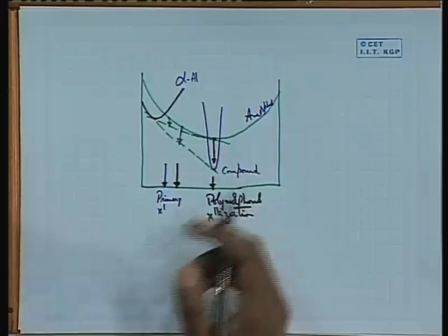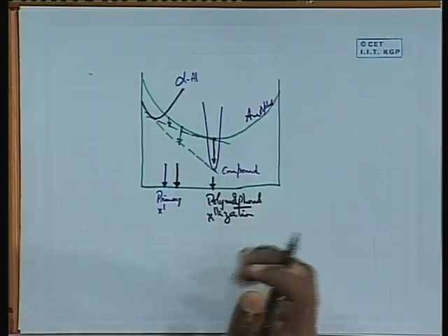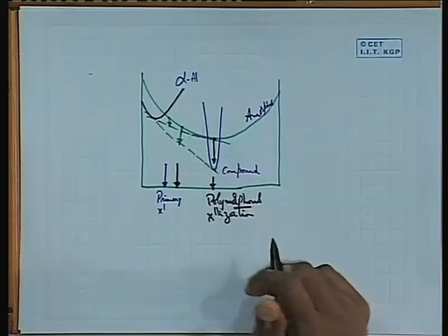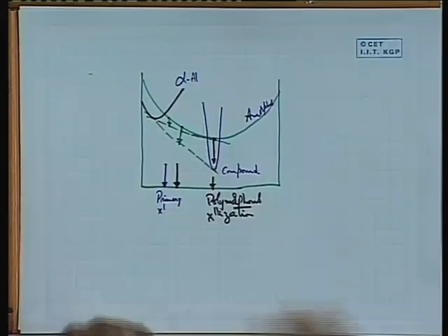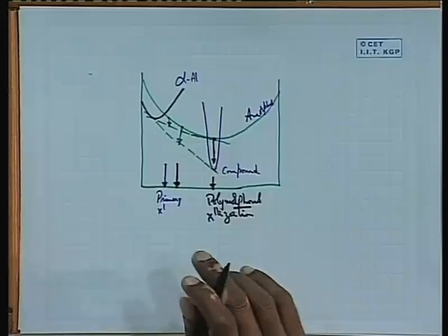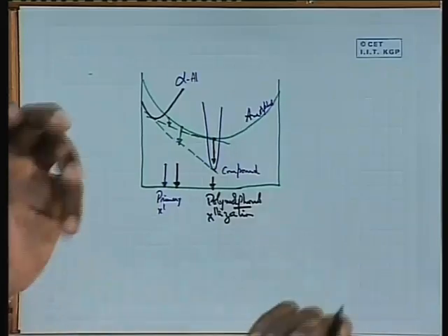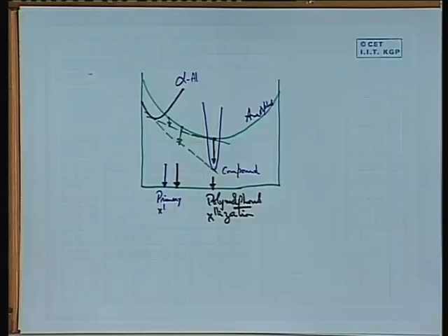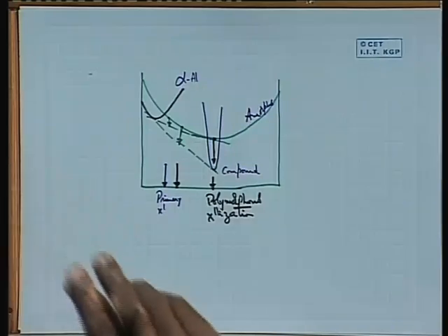Okay. So, this is what is called polymorphous crystallization, where the composition remains the same. This is one type of crystallization process for the amorphous alloys, and that can lead to a number of intermetallic compounds depending on the alloy composition that you are choosing. And for these compounds, if you can control the temperature and time of your aging treatment, you can have very fine precipitates of these intermetallics coming out and can give you what is called a nanocomposite, with nano intermetallics distributed in an amorphous matrix.